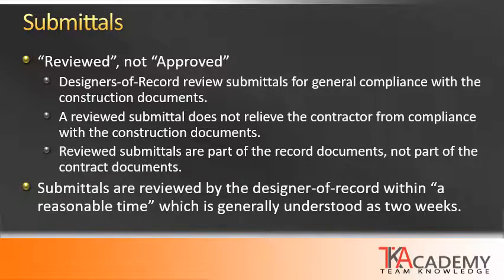A key role that architects perform during the construction of a project is the review of submittals. When an architect produces their design documents, it conveys the design intent, but it does not get into the specifics of fabrication of certain products, components, or systems. That is the purpose of submittals.